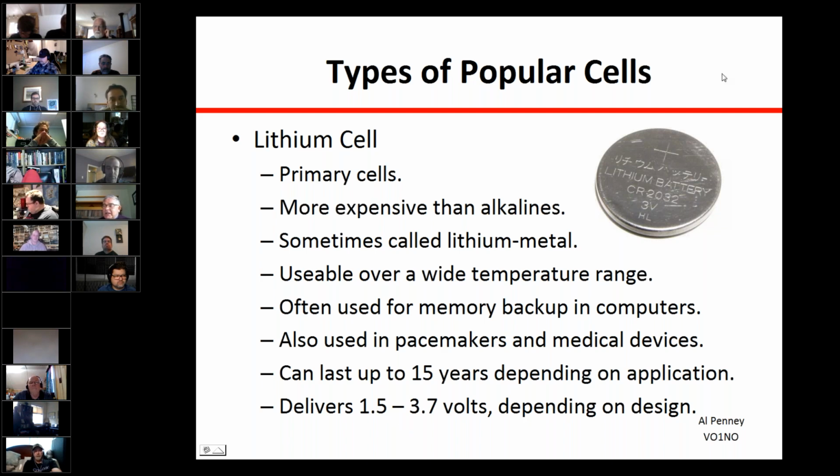The voltage depends on the chemistry of the cell itself, the materials that it's made of, and that the electrolyte is made of. So, the voltage is a set parameter, no matter how big or how small you make the battery. If you have that chemistry, that certain setup, then it's going to be fixed. The voltage is determined by just the chemistry. But in general, the bigger the battery, the bigger the cell, the more capacity, the more current it can provide over a longer period.